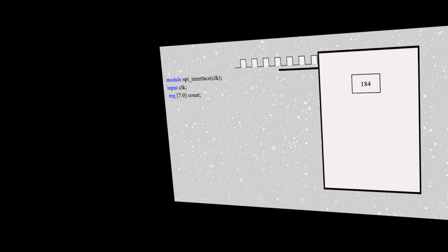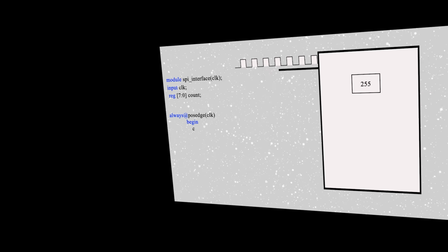in the process. We can begin to look now at how to write this interface code, and the first thing I'll utilize is the cyclic nature of this code. One of the things we can do is make a counter, an 8-bit counter, and that will give us 255 counts, or 256 if you include 0. So the first thing I do is let's have a cycle of 256 counts. Doing this allows us to look at what the value of count is, and then we can do specific things at specific times in the cycle.